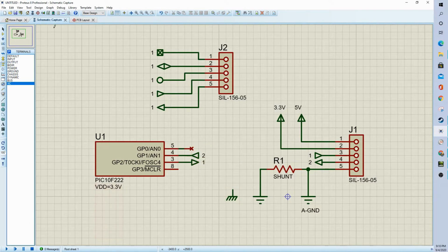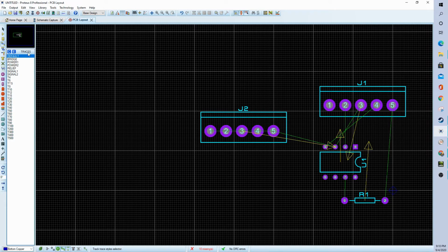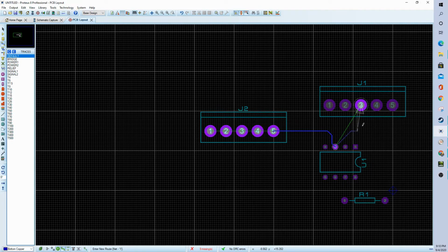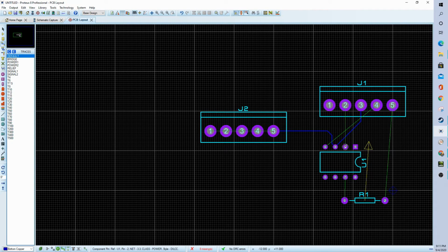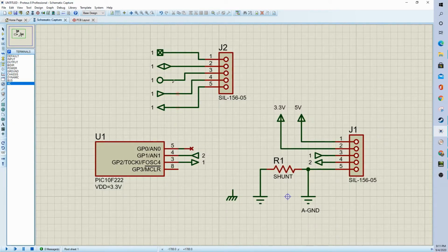Like so. When we go to our PCB, it's going to connect 2, which is an out, to a 2, which is an in. So if this helps you in any way to do your layout, then bless you, go for it. It really is something that you can manipulate however you wish. Just keep in mind that they are connected, regardless of the type. Now, you do want to be careful connecting these to power rails, but that's a different thing altogether.